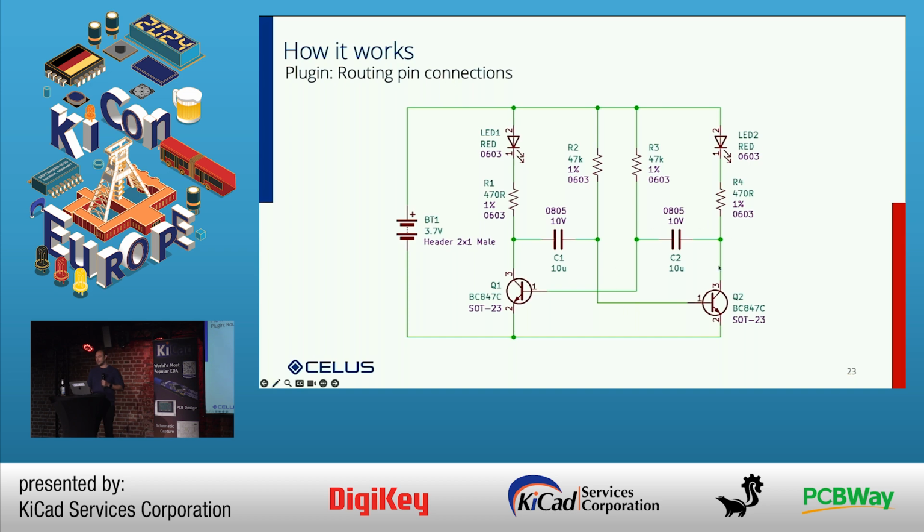And we can do that by using algorithms for Manhattan routing, which is the algorithm that usually does this 90 degrees routing between two different points. And with that, we have the connection between basically all the pins, just like represented in the graph file. We have the connection in the schematic file as well. And then we have something that can be exported and presented in KiCAD as a schematic file.